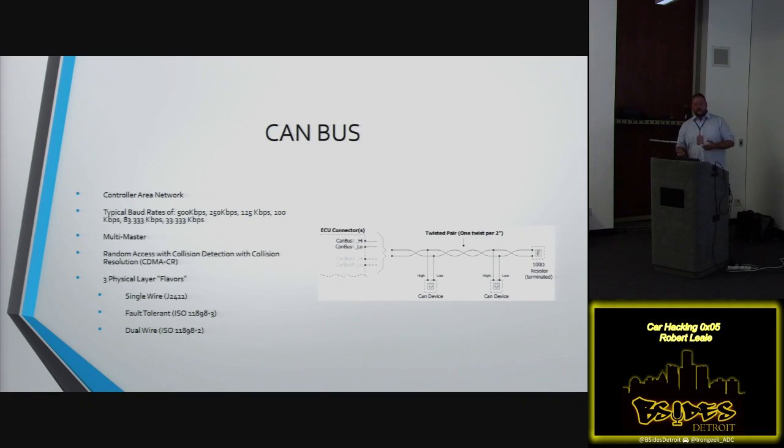I don't have a slide here with it, but they're coming out with a new version of CAN bus. It's called CAN FD. Because 8 bytes isn't enough, they're increasing the maximum size up to 64 bytes of data, but they're changing the baud rate mid-message. The beginning baud rate is 500 kilobits, then you switch over to 2 megabits, and then you're back to 500 kilobits. They're keeping the frame duration the same, just increasing the baud rate during the data portion of the message itself.